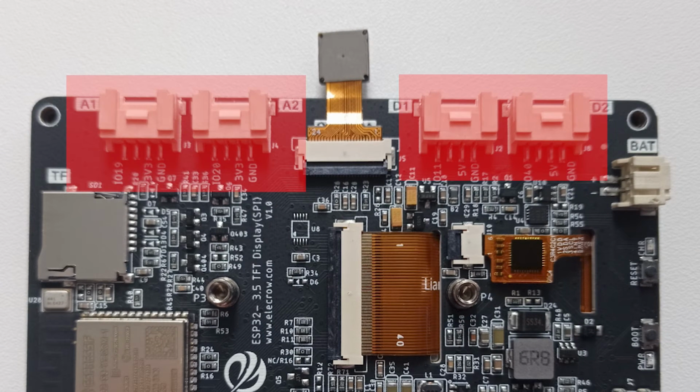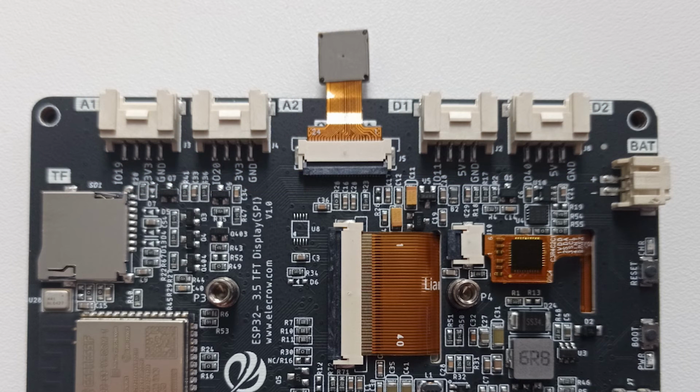If we take a closer look then at these I/O ports, we can see that each of these Crowtail connectors simply provides a power line, 0 volts, and then one of the ESP32's I/O connections. The only difference between the analog and digital ports is that the digital ports provide 5 volts, whereas the analog ports provide a 3.3 volt output. Now, I guess this simply makes them compatible with Elecrow's Crowtail sensors, but in reality, it does give us 4 general purpose I/O lines in addition to our I2C interface for expansion.